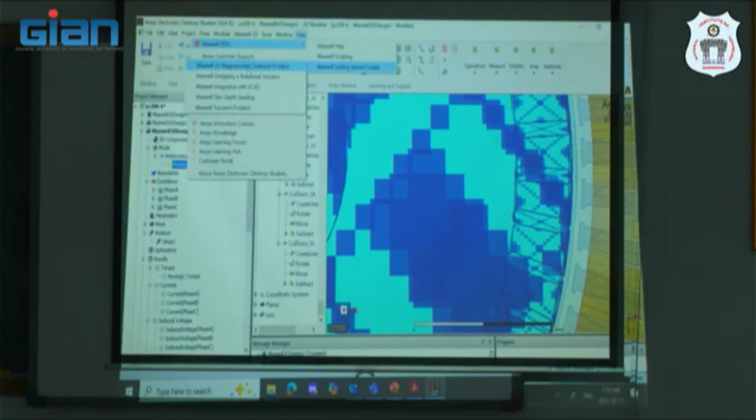Always start with that. Once you know how to build and run a magnetostatic example, go into transient analysis, the Maxwell transient problem example. So don't start with the transient problem, because that's not how you learn. Start with magnetostatic, do the first 1 or 2 examples, then go into the transient problem and try to do the analysis. And just for your information, although I have shown an example of only a motor, this software can also be used to model your high frequency power converters, especially your inductor, your transformer, or high frequency systems.